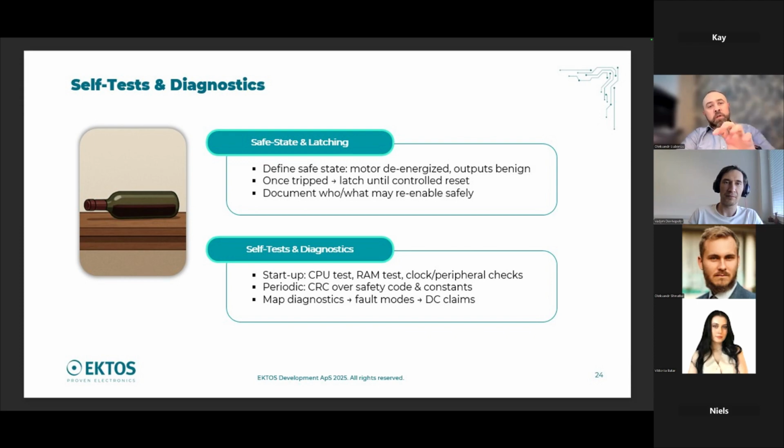And then it allows you to configure this peripheral to test specific parts of the RAM by blocking other peripherals from accessing those parts of the RAM. And then it works, extremely simple. You can just configure it once, and then you just need to respect that such a test may occur during runtime, and just remember about that. It doesn't make major problems. So that's just what I wanted to add.